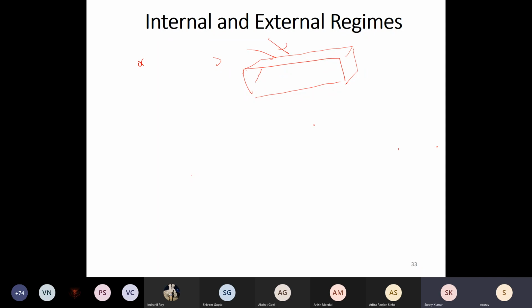And the evaporator coil is placed in this configuration. So somewhat like this. It is not vertically placed, it is not horizontally placed, it is placed at a certain angle, around 45 to 60 degrees. And if you look at it from this side, it will just look like a triangle. So the tubes are bent all along this surface, and then it comes back on the back side and again gets coiled up.